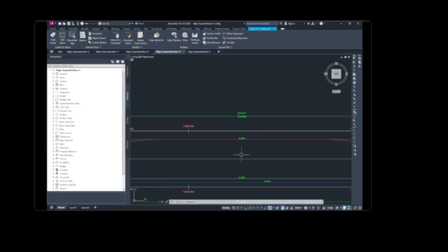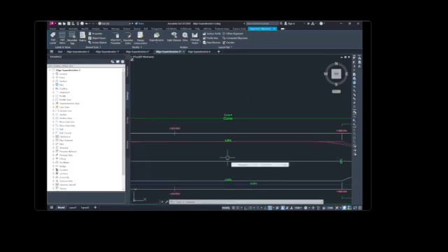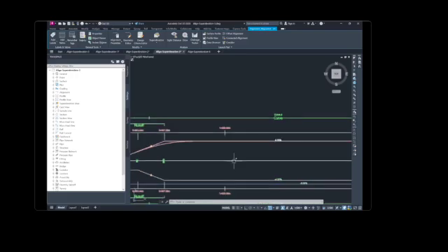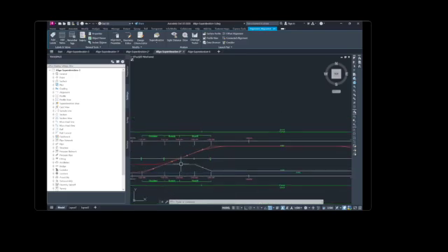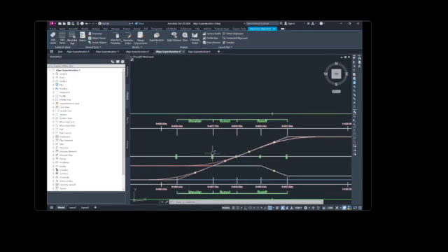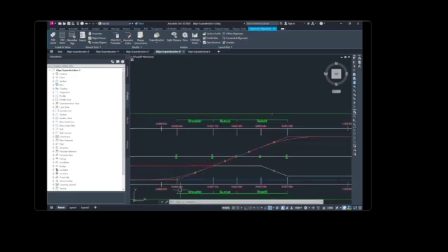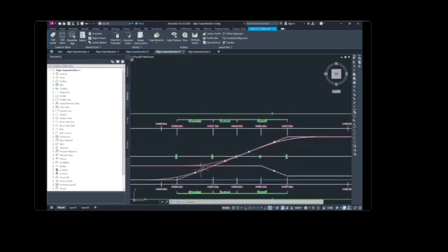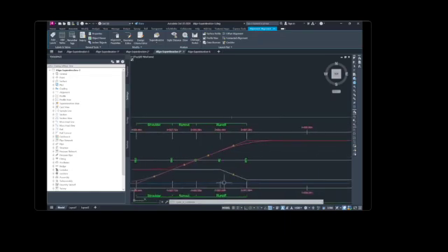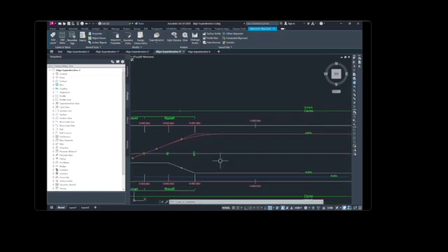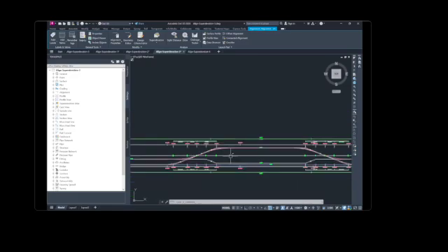In curve 4, notice that there is a curve where each line transitions in or out of a super elevated state. Curves are present on this super elevation curve, but not the others, because you selected the curve smoothing option during exercise 2.